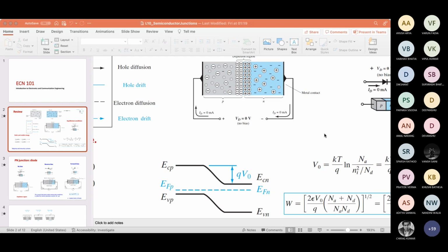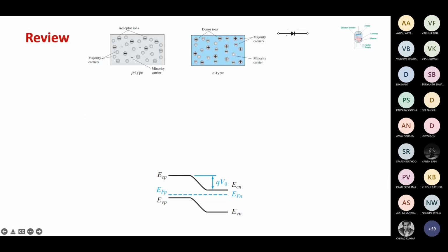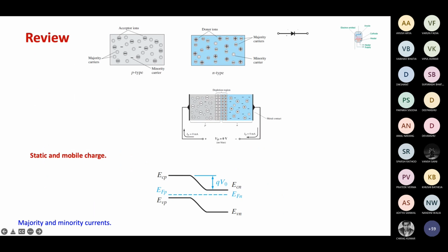You would ask me for an example actually. So the example is that if we shine light on this PN junction just on the P side, let's say we have covered the N side, it will create carriers in the P side and it will change the Fermi level. And if we shine light on the N side, similarly, it might change the Fermi level. Or the other way is if we connect a battery, it might change. Or if we put this diode in a circuit where a battery, resistor, or other electronic components are there, then also it can change.